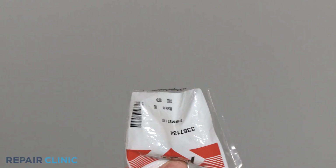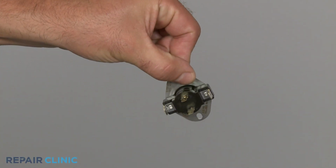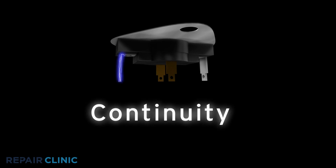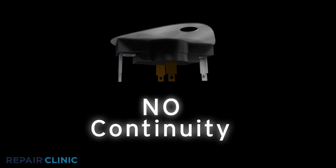A cycling thermostat is a switch that is actuated by temperature change. If your dryer does not heat at all, you should test the thermostat for continuity at room temperature. A continuity test will determine if a continuous electrical path is present in the thermostat. At room temperature, the thermostat should have continuity. No continuity means the electrical path is broken and the thermostat has failed.